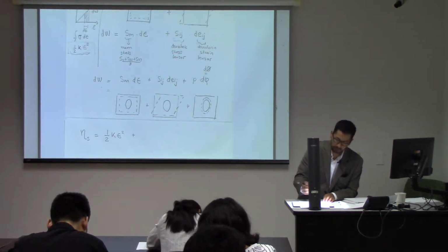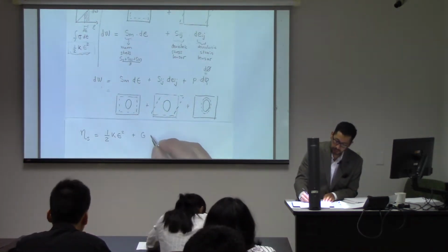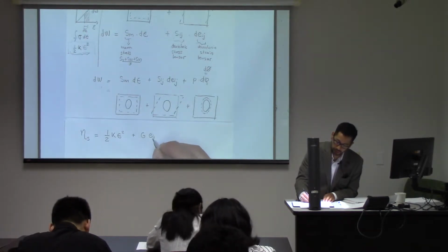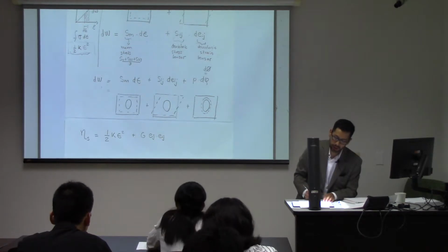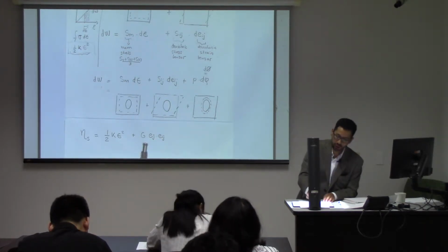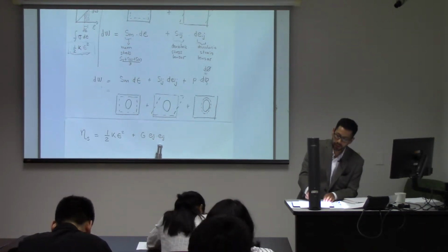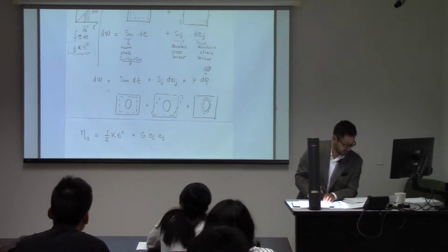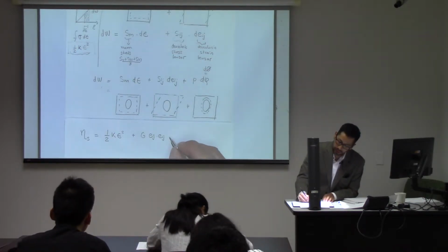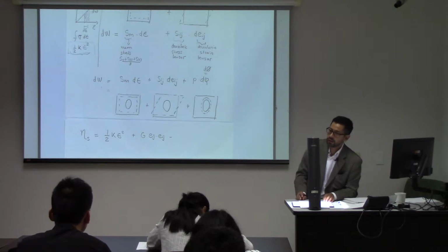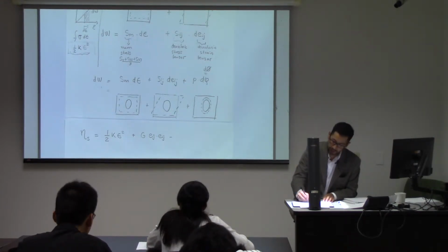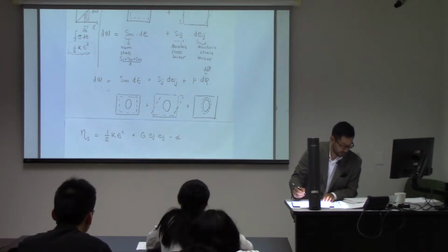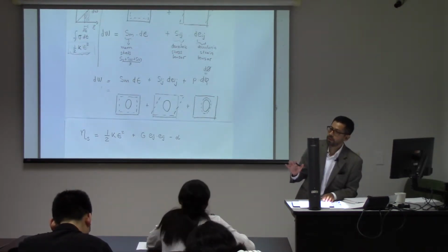This is the contribution of the mean stress. This is the contribution of the shear strains. So shear modulus now times the shear strains. Here I'm going to subtract the contribution of the pore pressure part. And notice that I'm going to introduce a constant that I don't know what it is, okay?